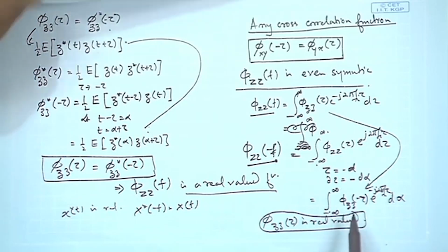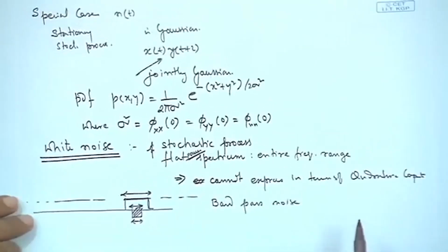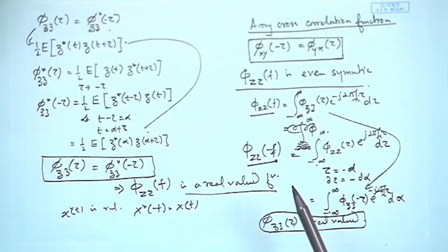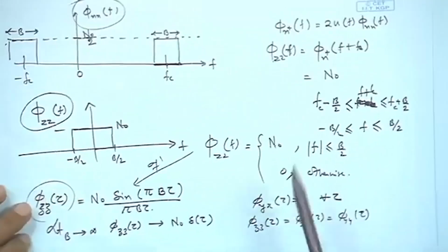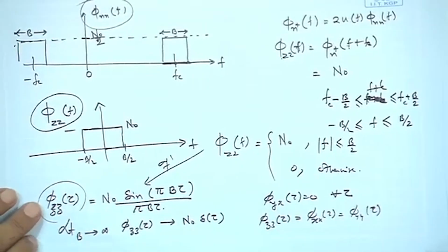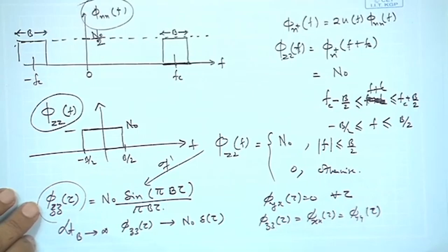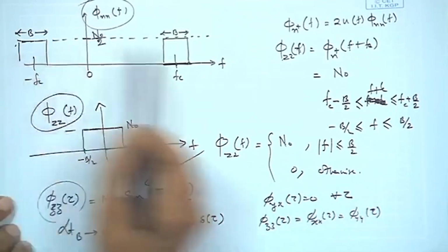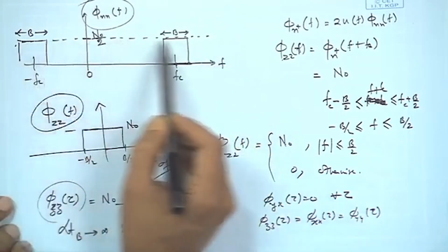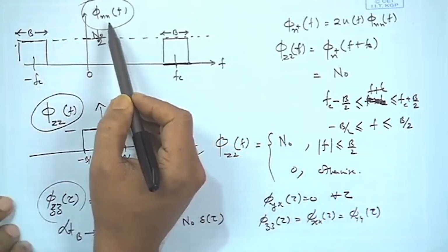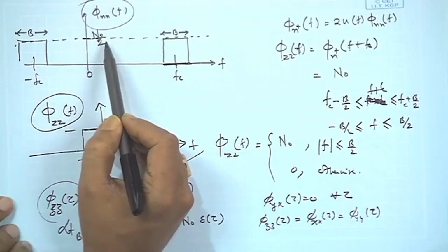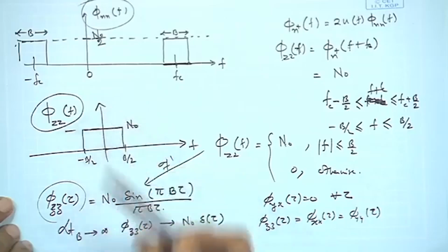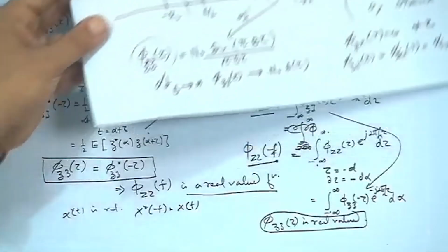So, that to be even symmetric, and when we were calculating the stationary noise process and we arrived at this, we use these particular relationships. In fact, that is not directly needed as well. Anyway, back to this point, that generally there is a confusion regarding this power spectral density. You should remember that in the pass band it is N naught by 2, whereas in the low pass equivalent it is N naught. So, that you should correct it.